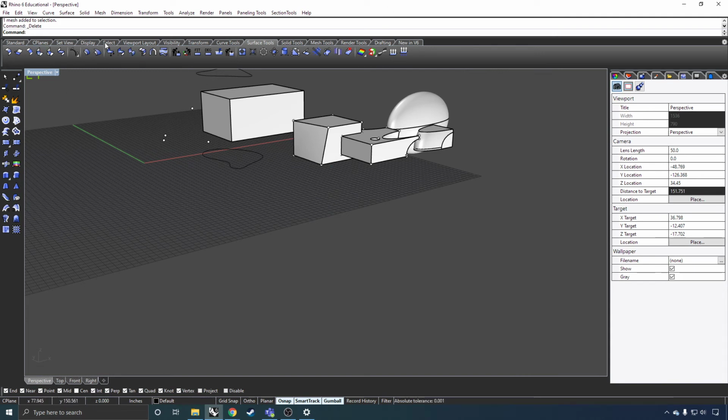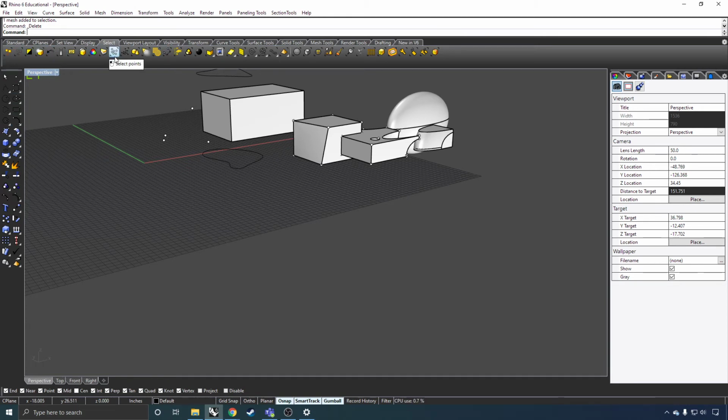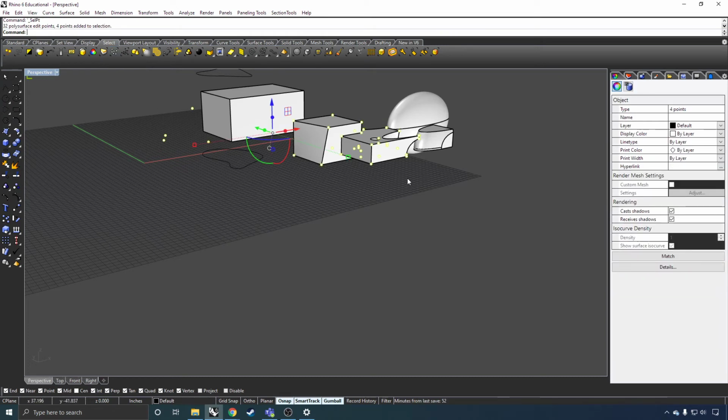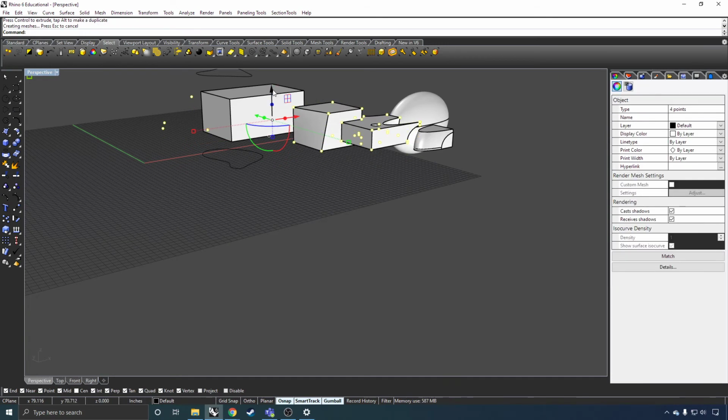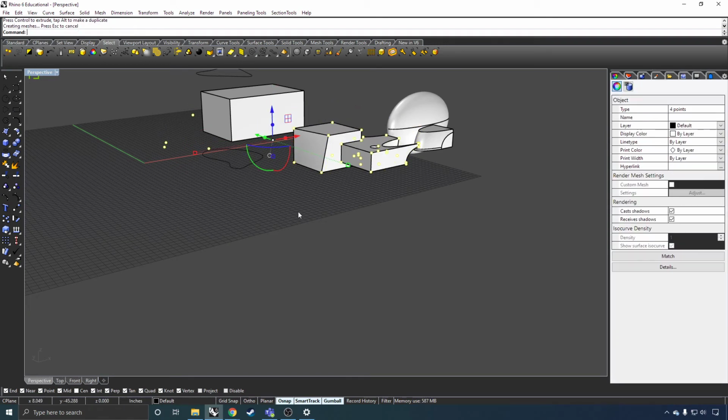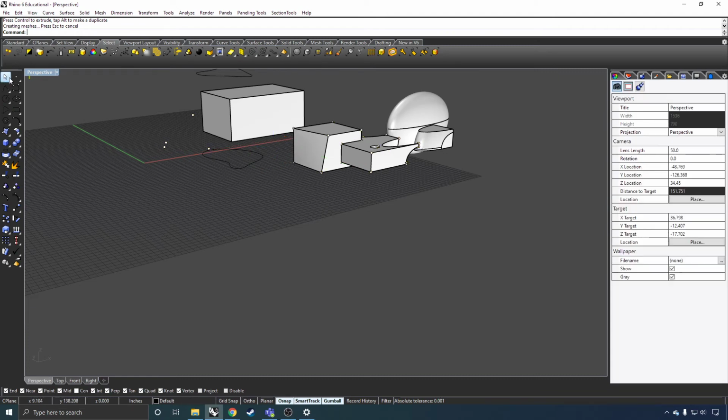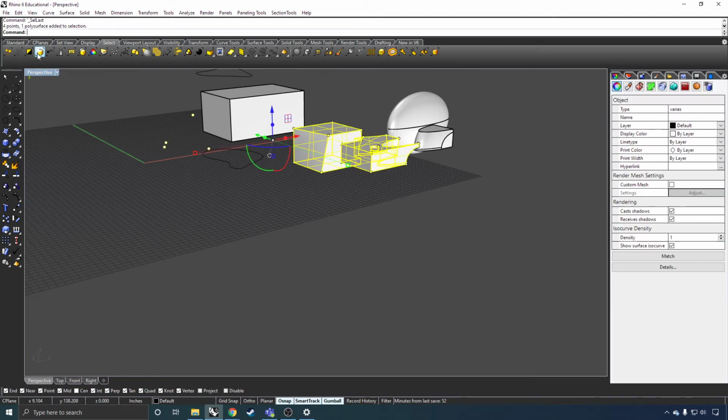The other things that I want to show, and we're going to try to go quickly through this, are the selection tools. So this is giving you the standard tool set on the left, but you have all these selection tools up here where you can select just theoretically all the points. So it's pulled all of those individual points, so I can do anything I want to with them as a unit. This can be really useful in Grasshopper because you may only be dealing with a small subset of information, but you may only want point data or line data. You can select the last created object, which was this one. That's sometimes useful if you get lost or forget what you were doing.